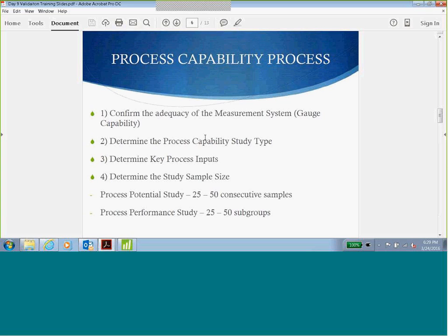Because when you're doing your OQ, writing and executing your operation qualification validation, it's just going to be testing out one production equipment using the same lot of material or the same raw materials. Whereas in your PQ study, you'll be using multiple equipments, multiple operators, multiple production lines, so you'll be including that variation. Usually your PQ protocol will be referred to as process performance, and in your OQ you will be doing the process potential. But that is not always true.